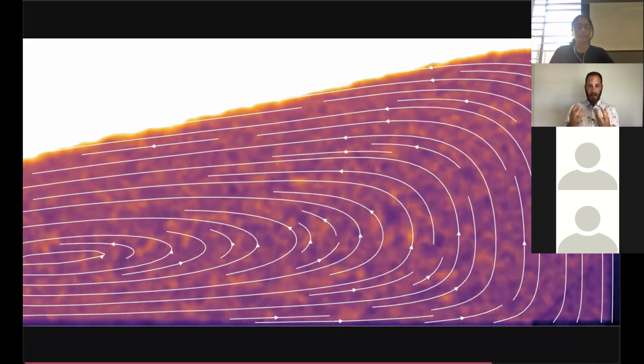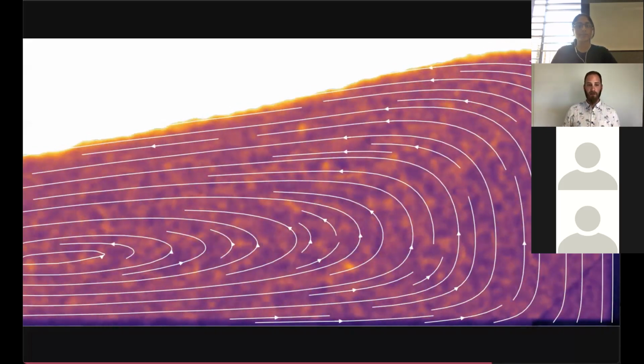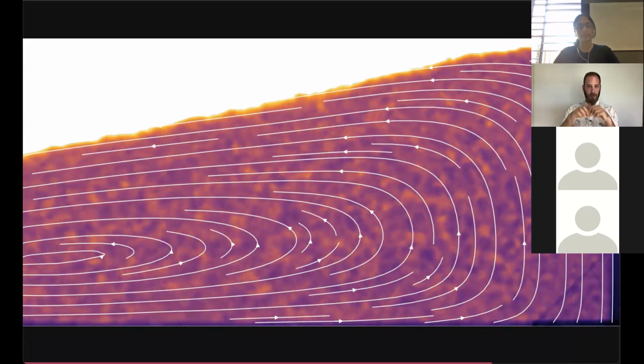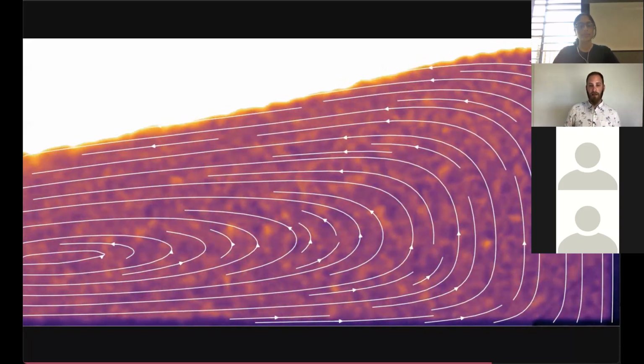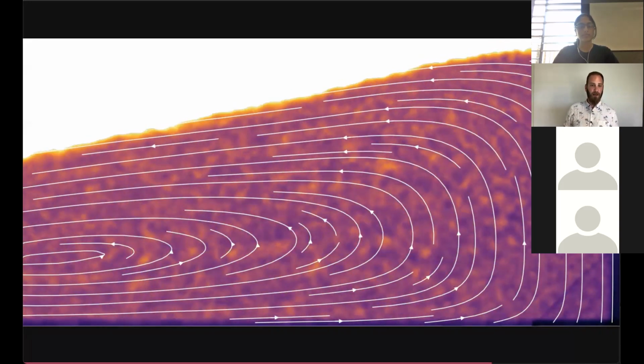And so now we can't make out individual grains, there's too many of them, but we can see fluctuations in the material. And so here, when there's small particles, we'd expect small fluctuations, and large particles, we expect larger ones. And so we can use these Fourier transform techniques now to go in and try to identify what sizes we have there.